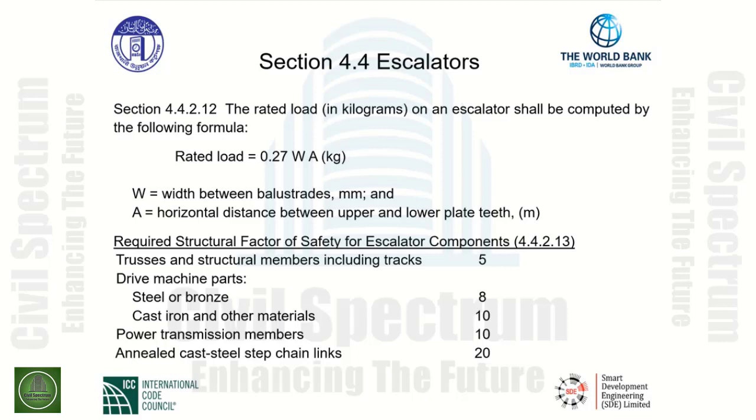The required structural factor of safety for escalator components in 4.4.2.13 is indicated as such. Trusses and structural members including tracks, 5. Drive machine parts, steel or bronze, 8.